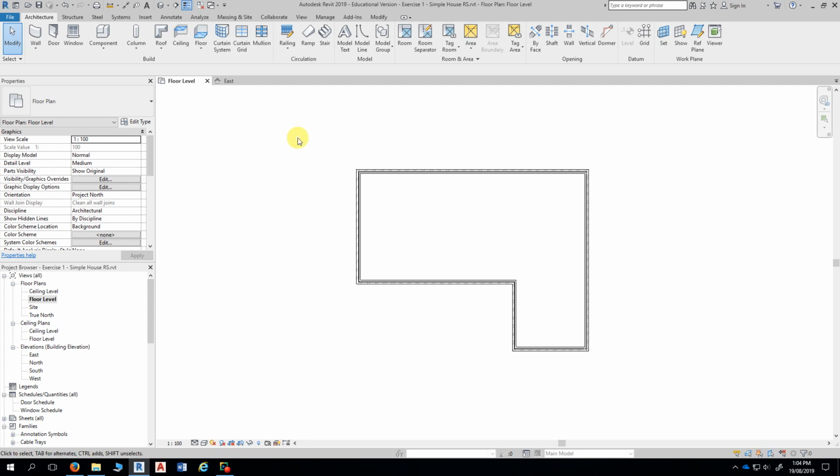But essentially, we now have to get the wall set out correct in terms of our overall measurements before we do anything else. There's absolutely no point in drawing your internal walls at this stage until you are confident that you have your wall lengths correct.